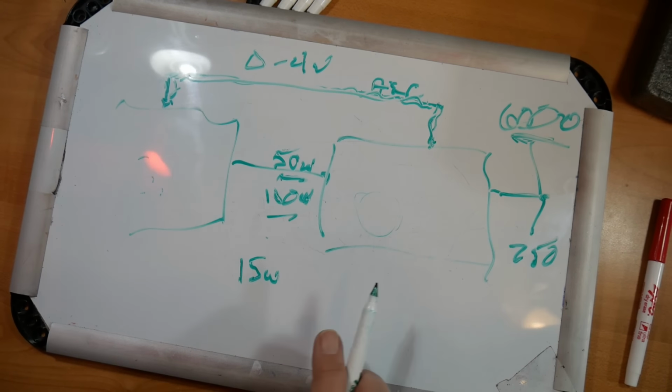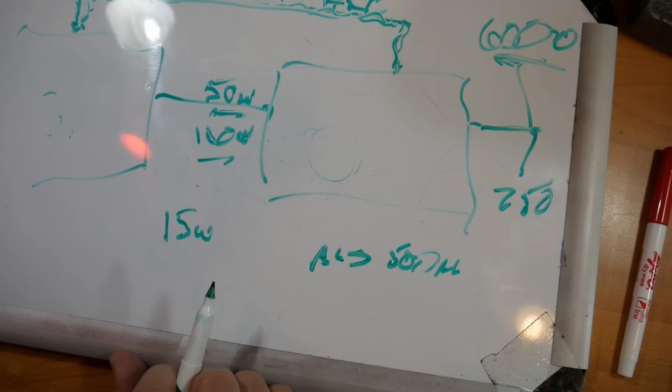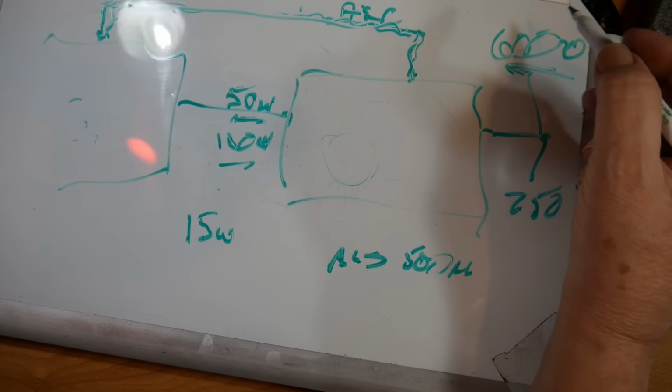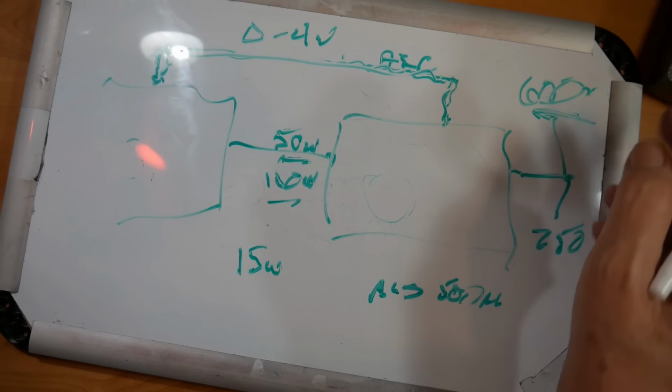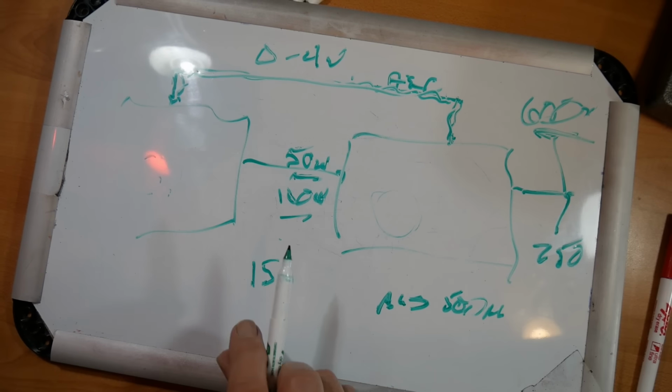As it turns out, my ALS 500 does not have this. So I had to go in and very carefully figure out what would give me the maximum power out, and it turned out to be 62 watts. So if I'm going to operate this amplifier, I have to manually turn the power down.